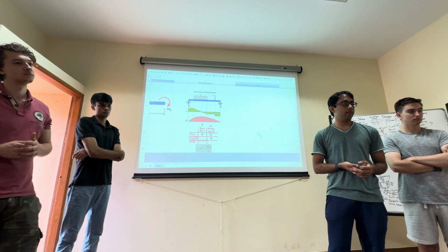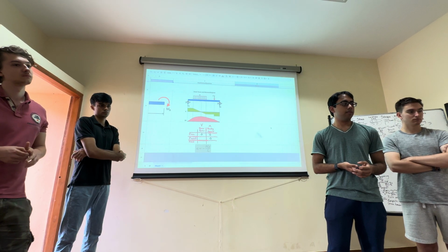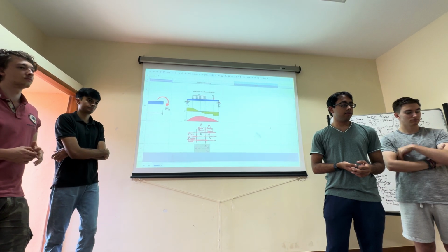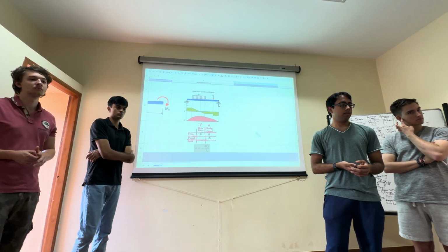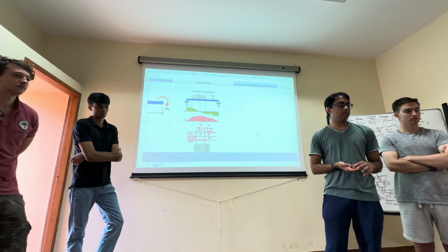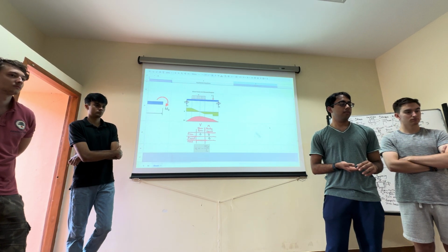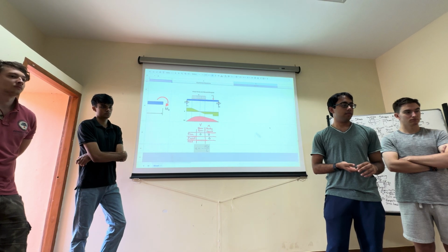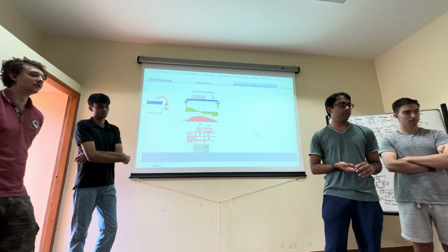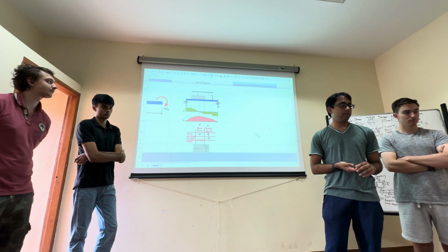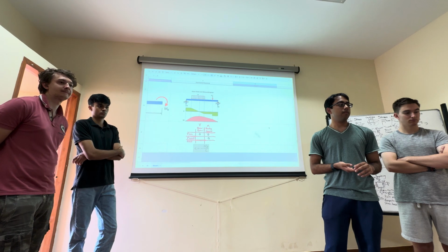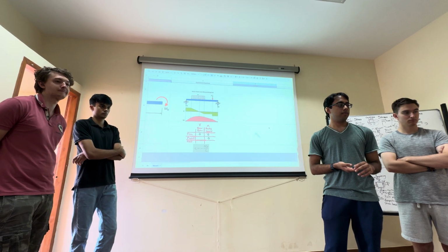But there are also boundary conditions associated with the load. So the particular area of the structure which is loaded in different manners. I could apply, let's say, a force over that cross section, which is kind of a distributed load. On the other hand, I could apply it with a sharp pin, like a concentrated load. Or I could bend it this way, which is like a moment, M0, that you showed over there. So all of those are also boundary conditions. They come under what are known as natural boundary conditions.